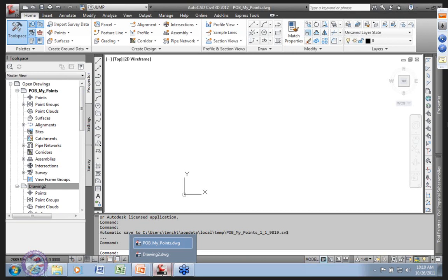We had points that exist in surfaces, which may be related to points if we use the LDT context in our old point database outside, but may or may not be related to it anymore. We have these things called COGO points in Civil 3D, which are the point feature, and then we have survey points, and if I keep pointing it out, we will find that there are lots and lots of other points.